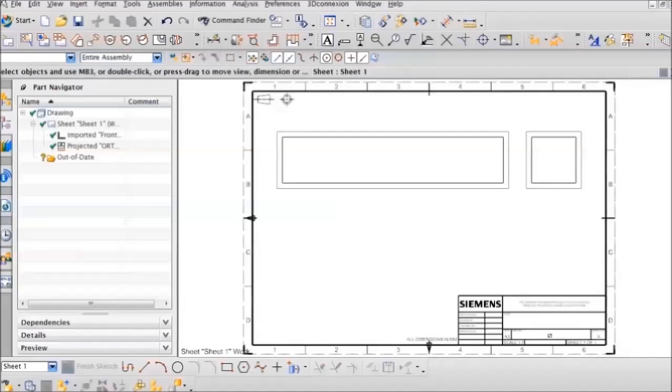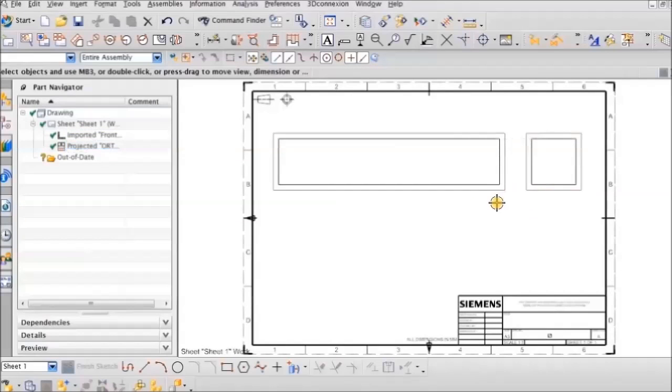Tip number one is related to correct positioning of the views for a parametric model. As you can see, we have two views and they both fit properly in the drawing border and in relation to each other. The first thing that you would notice is that the model is quite simple. That is done because it's much easier to define your views when you have very simple geometry.